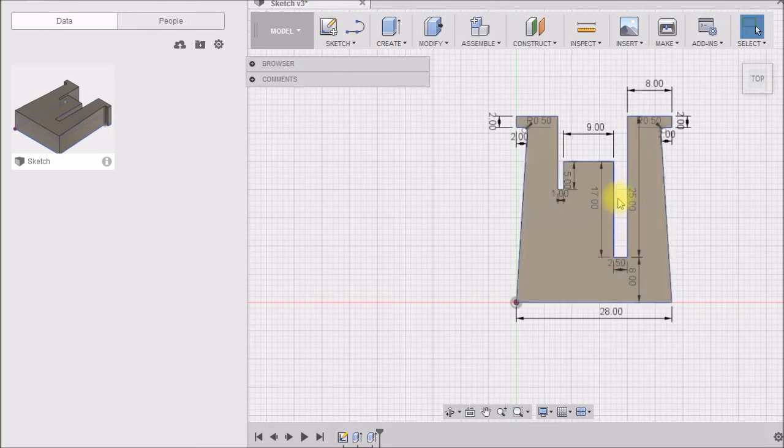So this is the trim ring flange. It's 2.5 millimeters thick. There's a 9 millimeter recess in the light, and then there's this 1 millimeter thick metal flange or cover on the back. And then I just built the clip to fit around that and to fit inside of the accessory clamp that I'm using to hold this. So that was my final part.